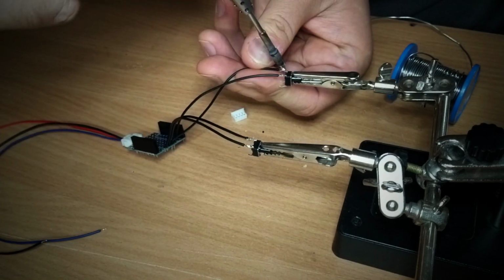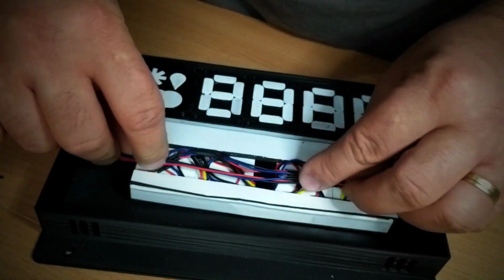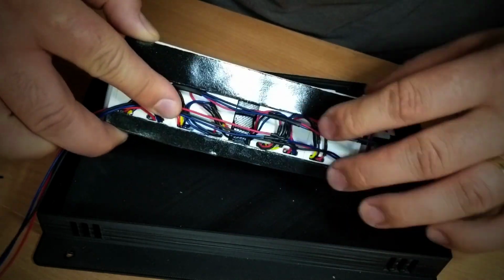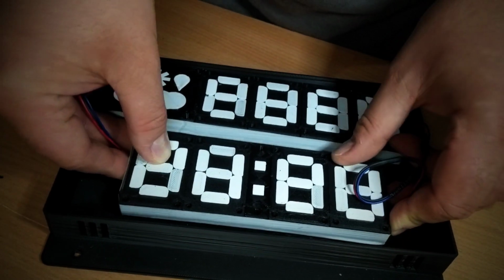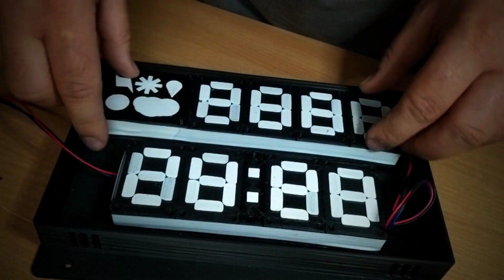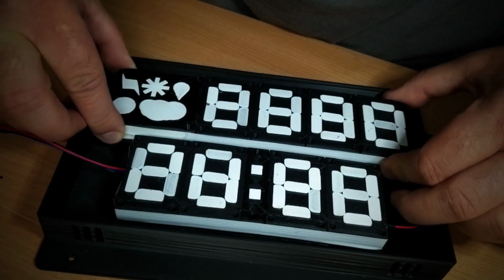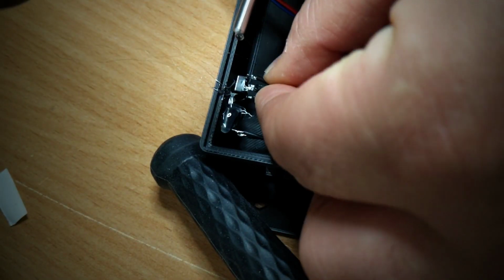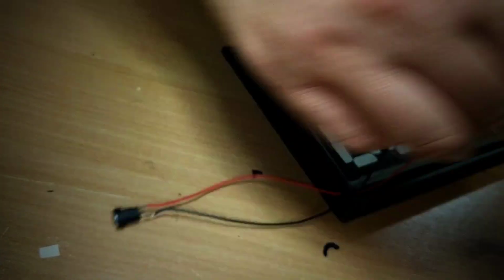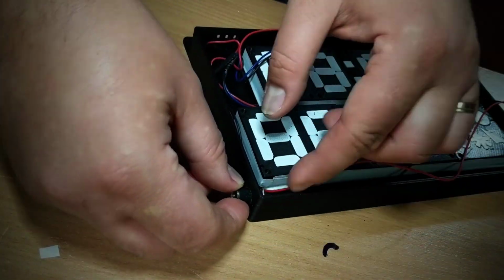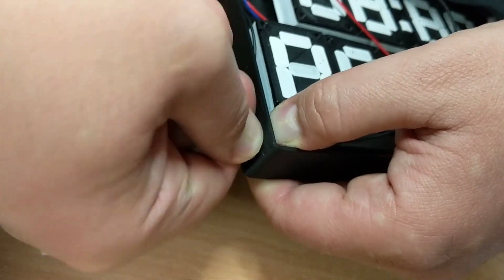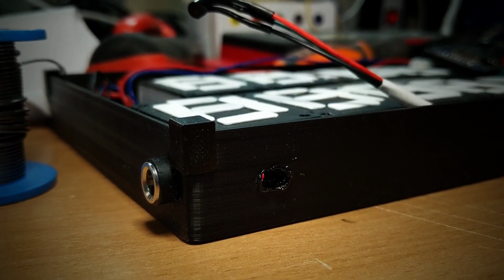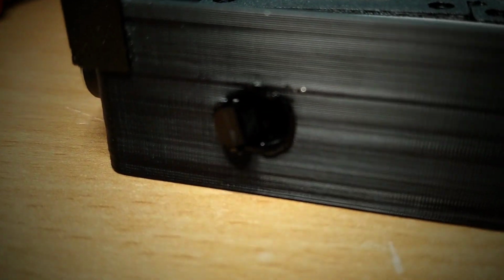At this point I had everything to finish the clock itself. First assemble the display segments. Then secure them in the housing with double-sided tape. After that was done, I hot glued the buttons in place and added a DC plug to power the whole thing. As an afterthought, I added an external temperature sensor to measure the in-room temperature and display it on the clock.